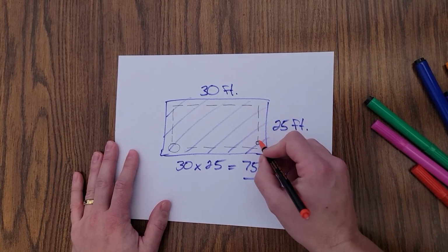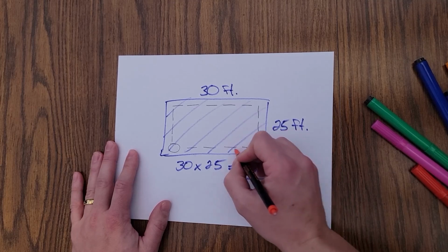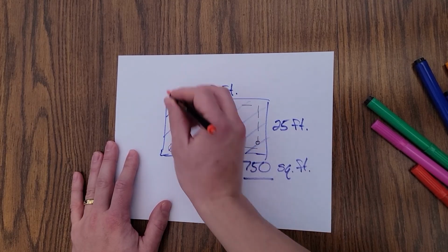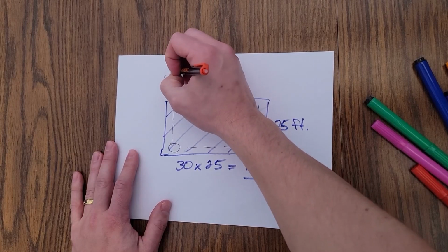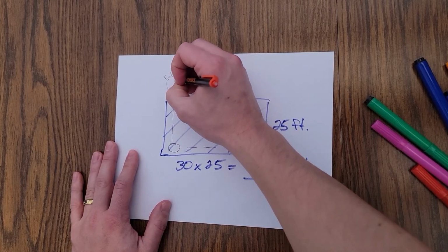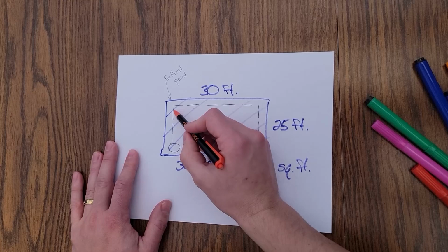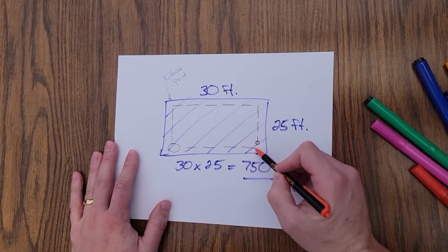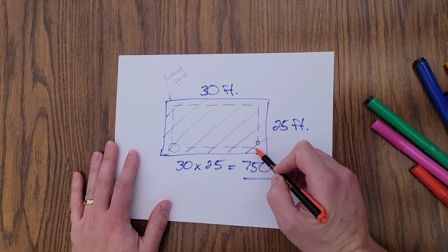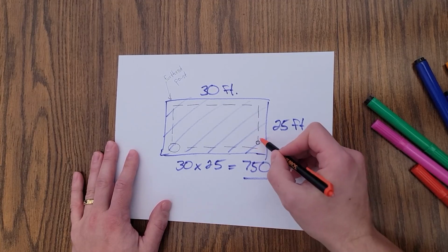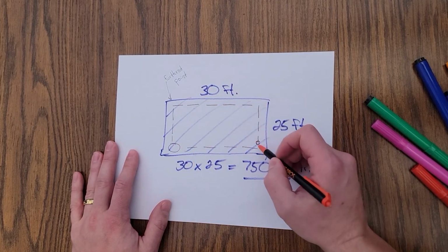And basically what you want to do is you want to take the longest distance, or go to the furthest point, which is across. So this will be the furthest point here. And you want to use this length because what you're looking for is the farthest run of piping, and this is like the same path of travel here.